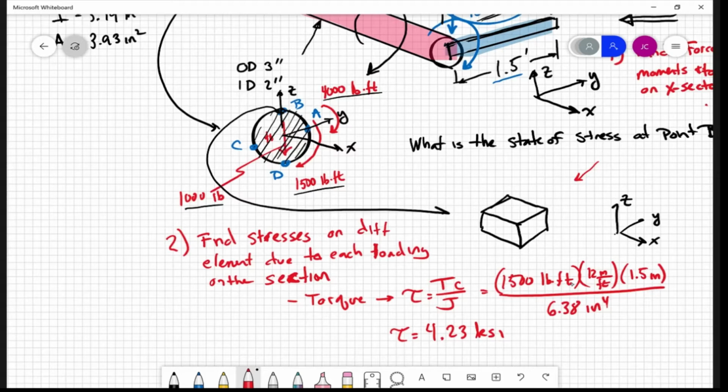And if that's the case, the traction it's going to put on the face at B is going to go to my left, your right, okay? And if you want to think of it, that's acting on the front face at point B. What's showing here on this disc is actually acting on this face. So it's going to be a traction that goes like that. Does that make sense? That's what's acting on that cut face due to the torsion.